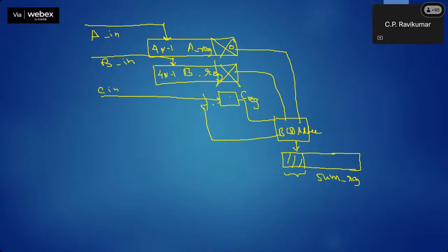So ideally, in real hardware, we may have a multiplexer, right? And depending on whether we are doing this in the beginning, if the reset is true, this will get loaded in the C register. Otherwise, the feedback from here will get loaded. So C out, and this is C in. So when the reset comes, there is a count here which will initialize to n.